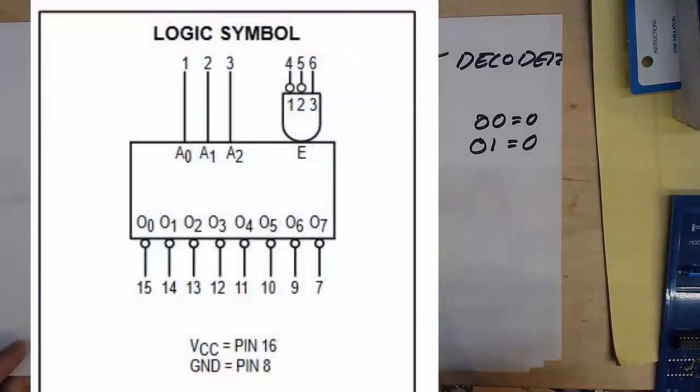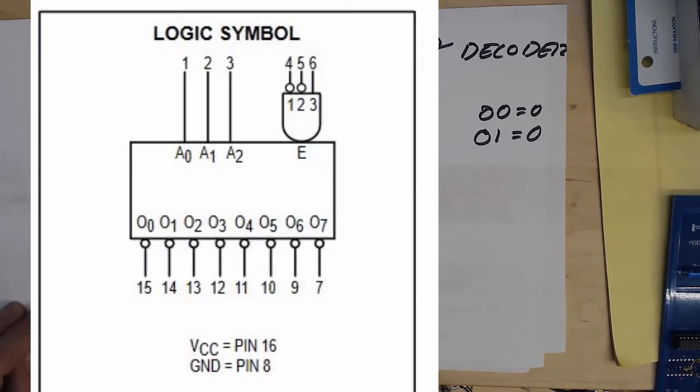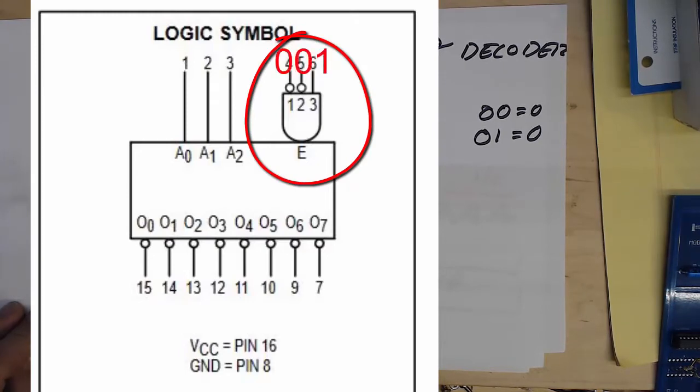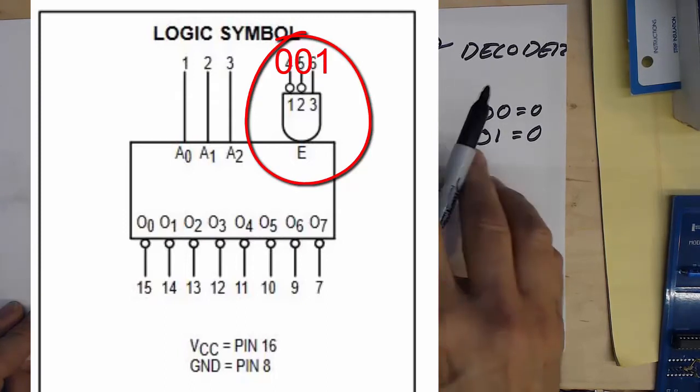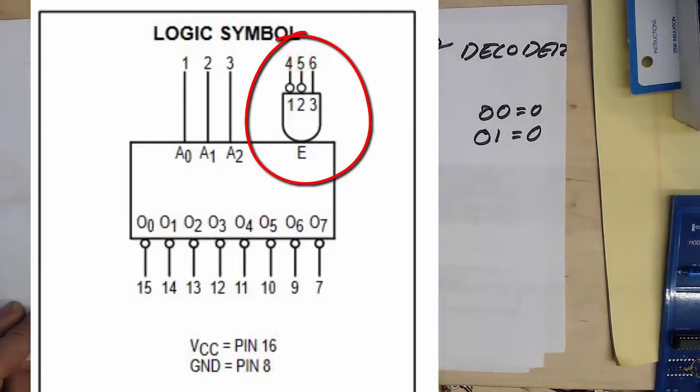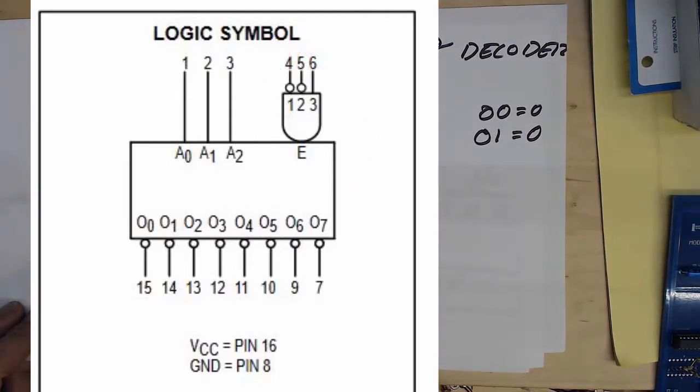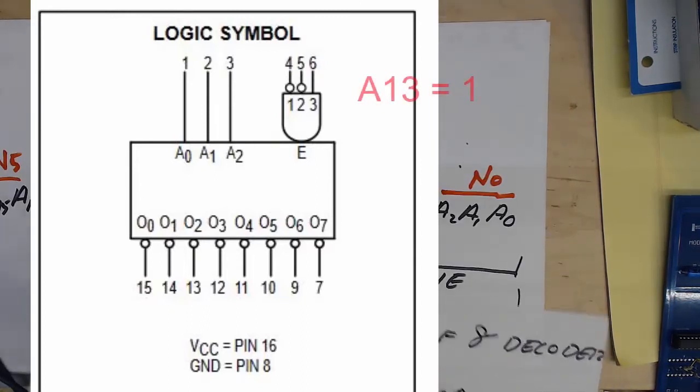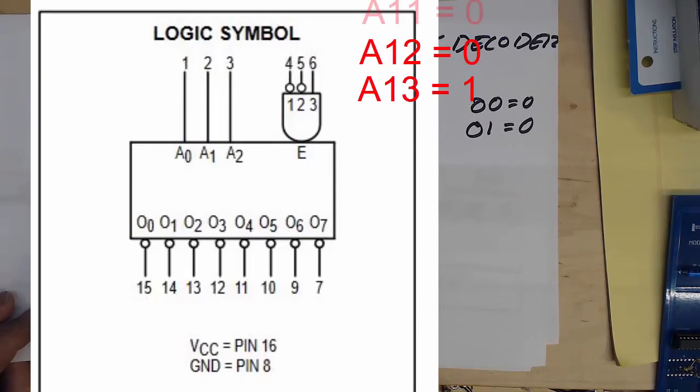And fortunately for us, the 74138 has given us 3 inputs, and those 3 inputs have to be in a specific pattern for that chip to be enabled, and by that chip being enabled, we're then inferring that the entire board is enabled. So all we have to do is have our 3 addresses, 13, 12, and 11, have this pattern 1, 0, 0, and that board is selected.